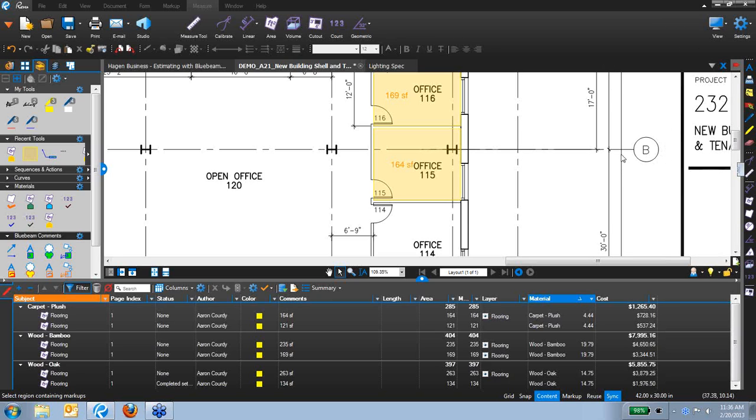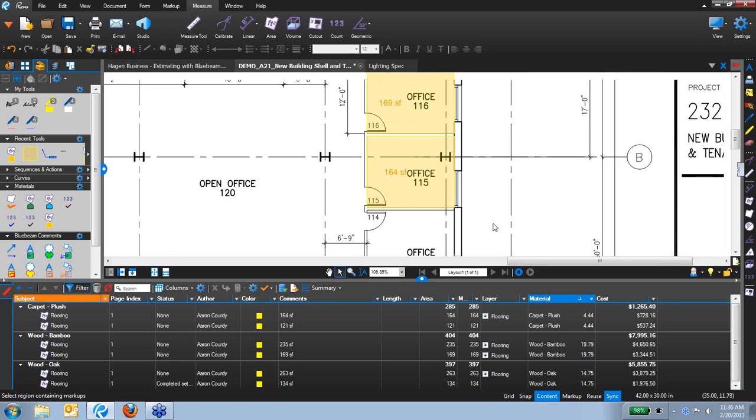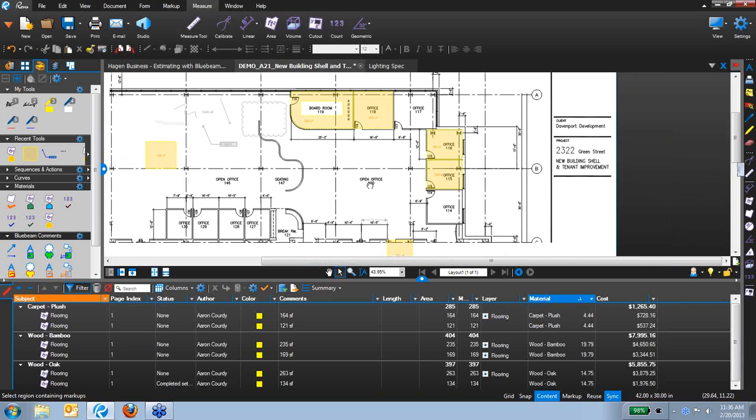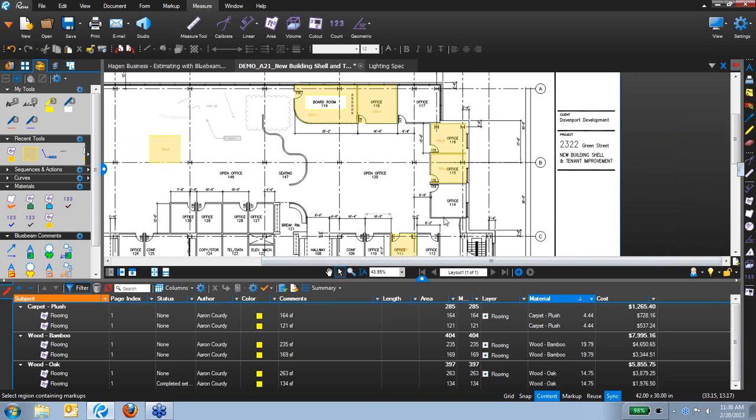All right, let's go ahead and just move right along then. Let me talk about how we have this information here in Bluebeam Revu and how we're going to use it a little further past the PDF document. I can take this information, however I sort it, filter it, etc., and create a report with exactly how I organize this markups list down here.